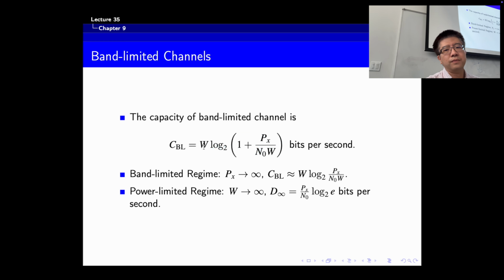The other thing is that in practice you may see this formula a lot without this W. In practice, we normally normalize by time and by the bandwidth, so it's called spectral efficiency. It's the number of bits per second per hertz. Because in practice for communication, we have 2 resources to use. One resource is time, and the other resource is frequency. They are related, not unrelated, but we have 2 resources to consider. Therefore, in practice, we normally consider bits per second per hertz.